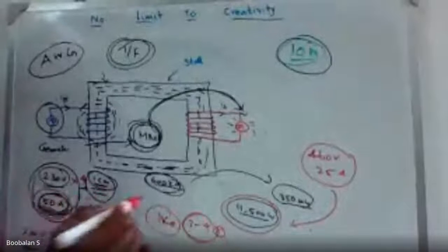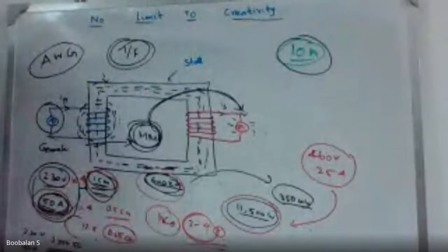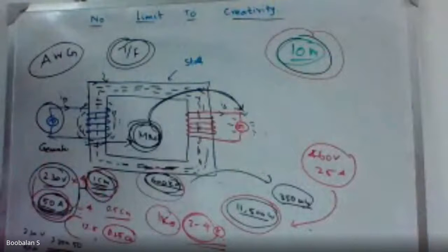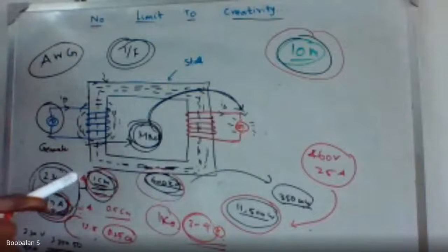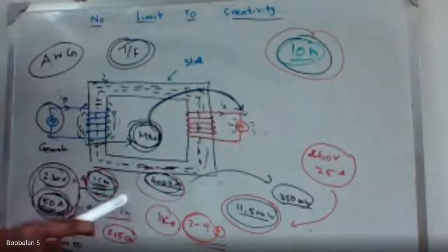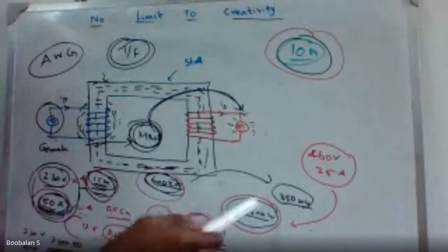Imagine 600 kilometers, if you are just having one diameter, what is the price, right? It will be a very, very huge cost. Just assume 10 meters of copper conductor, it will be an unimaginable amount. So for that purpose, we have an option: we increase the voltage and reduce the current. By doing this, we could reduce your copper conductor's thickness. In the same way, you could transmit.